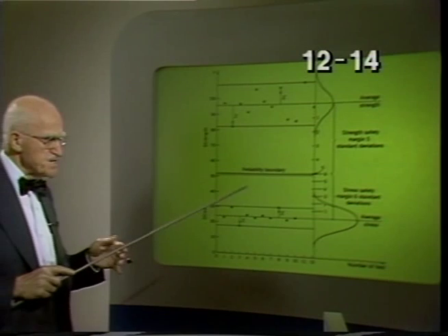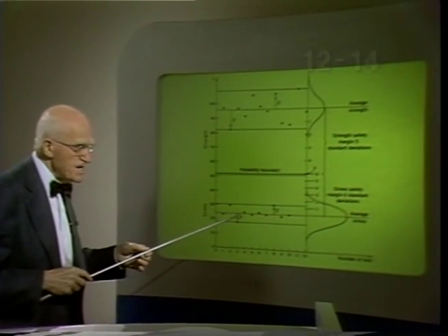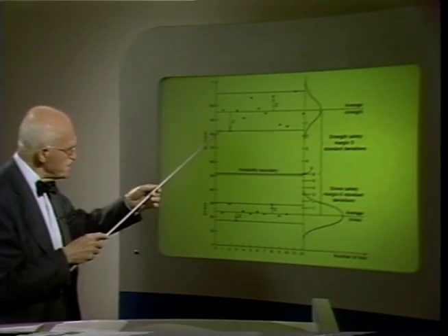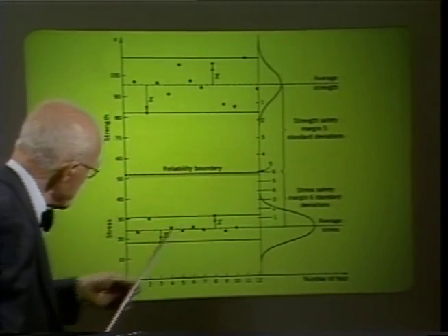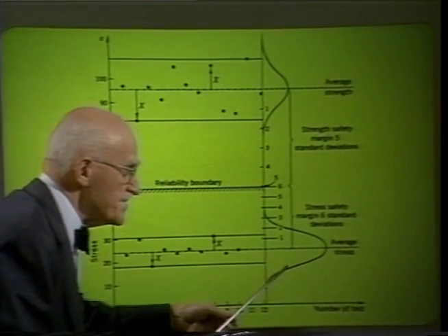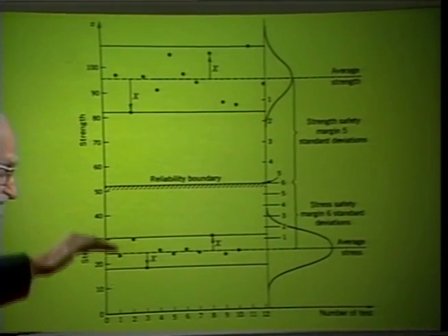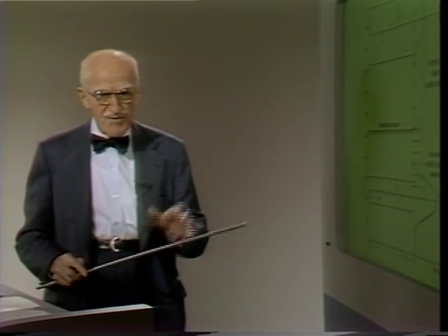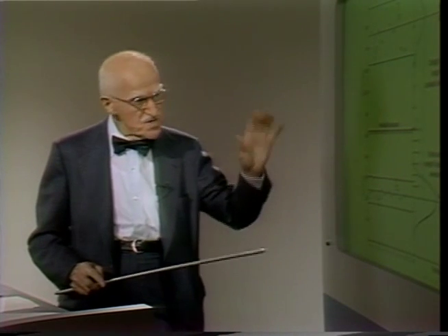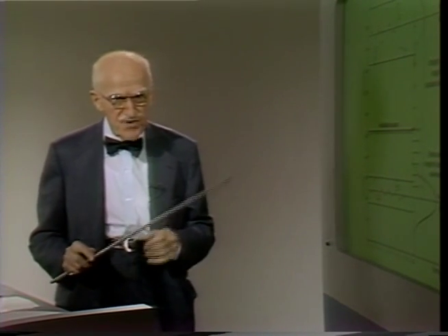Variations in stress and strength can be related to each other based on establishing a minimal distance between the two averages. The minimal distance is counted off in number of sigmas. If we are able to quantify the averages and sigmas, we can compute the expected failures in parts per million, or billion, or whatever.